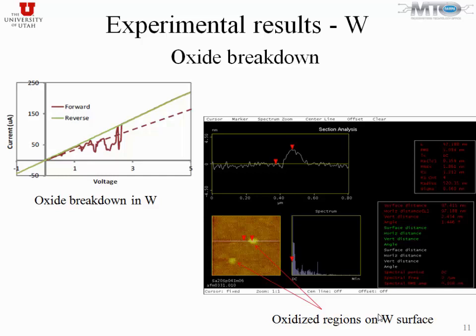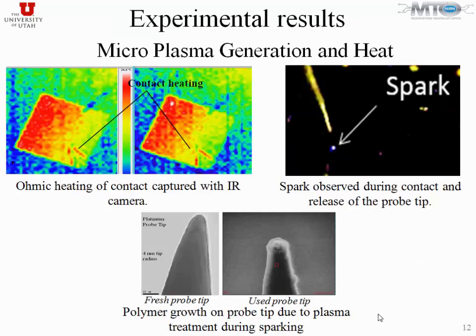And then in this cycle of the operation, you're growing anodic oxide. And if you go back in the reverse direction, you can break it down. Now that oxide can be broken down as you start increasing the voltage. So you increase the voltage between the tip and the sample, start growing anodic oxide. So that's when the current goes down and you see all this noise-like behavior. And then as you keep the voltage to higher values, you break down the oxide that you have grown, and then you get the rest of the cycle.